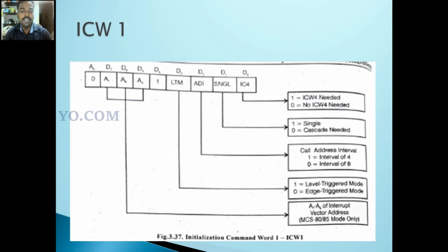Okay, if the 8259 acts as a slave, it needs a slave ID, because we are using more than one 8259 connected in cascade manner. One device acts as the master and the remaining devices act as slaves. If more than 2 devices act as slaves, they will need a slave ID, and only then can we identify where the interrupt is coming from.